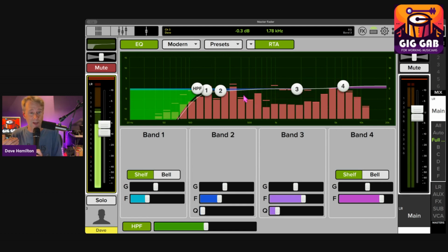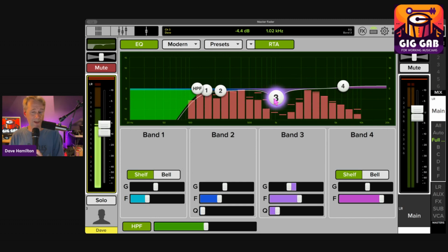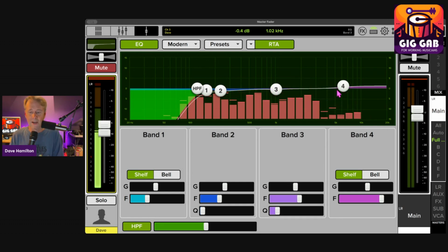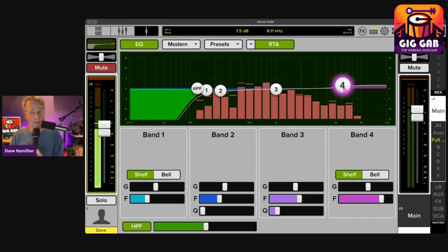Sometimes you have to. Sometimes in a pinch, especially with time constraints, that's the way to solve a problem. It's just like, okay, crap, I'm gonna pull out a lot of, whatever, 1K here, and maybe make a note of, like, for the next gig, get this person on a different microphone, right? I often will make the top, the highest EQ a shelf, so that I can either sort of pull all of the high end out or add a little bit of sparkle to the high end by increasing it by